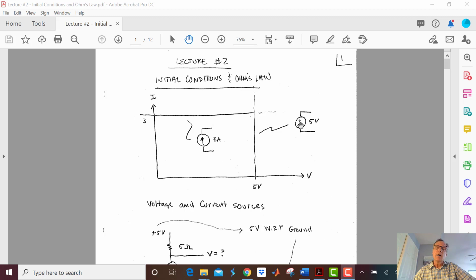Sorry about that. So if I put a 1 ohm resistor on the output of this, I am going to get 5 amperes. If I put a 1 micro ohm resistor right here, I'm going to get 5 million amperes, because the voltage source intuitively and verbally will put out whatever current it needs to make sure that there's 5 volts here. Let's look at that with a graph. I like to look at current versus voltage plots.